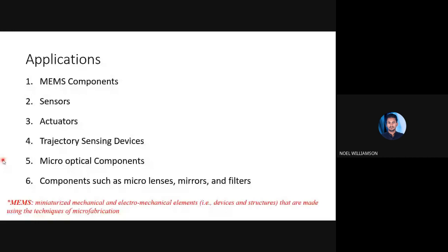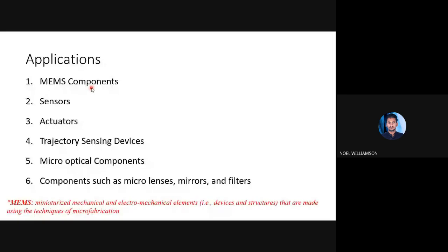So these are about the LIGA process. LIGA process is nothing but the manufacturing of microstructures by deep X-ray lithography. So this can be made from plastic materials or metals, anything. And mainly this contains three main processing steps. First one, lithography, then electroplating, and finally molding.